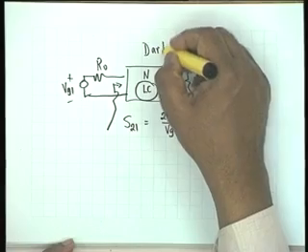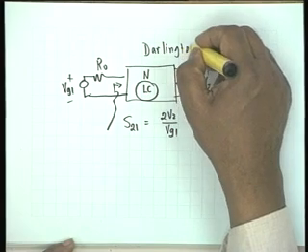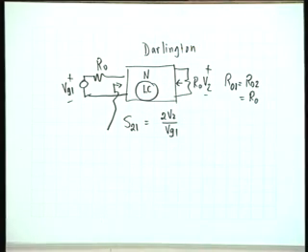You see, if both the terminations are unknown, and our aim is simply to transfer maximum power, then we don't have to put any network, all right. But this is a specific case, as I said, and it is a special case of the procedure of Darlington, of the problem that Darlington solved, and therefore this problem is known as Darlington's insertion loss problem.